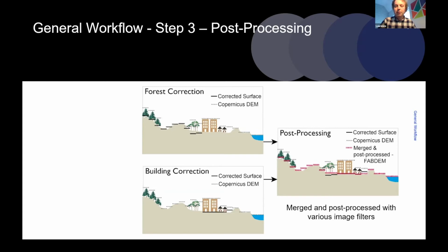So yeah, and it was quite challenging doing this, because if you're a bit too aggressive with your filters, you smooth out the DEM and you lose the benefits of having a 30-meter product. You might as well just be using MERIT or something similar, but you need to be aggressive enough that you manage to get out these artifacts which are undesirable.